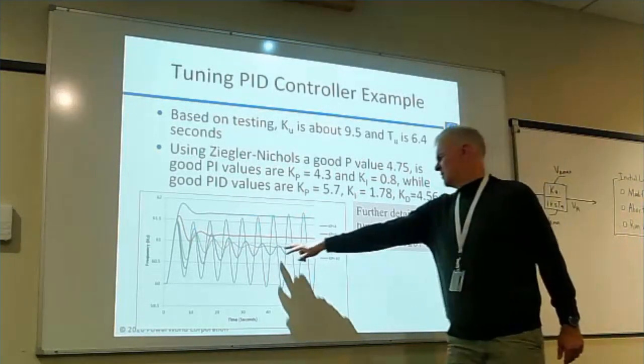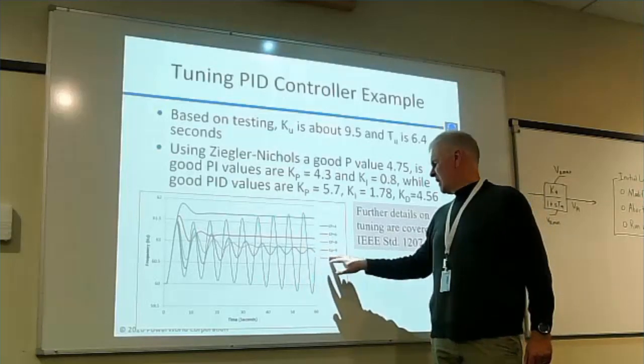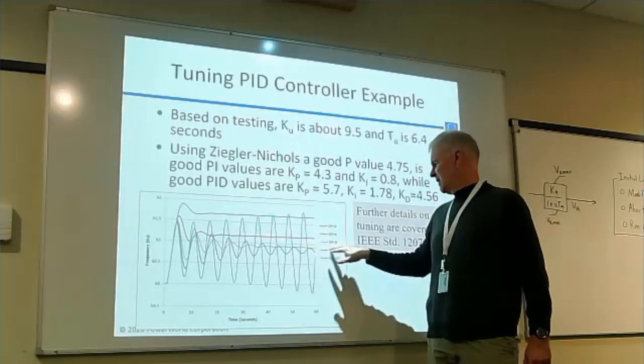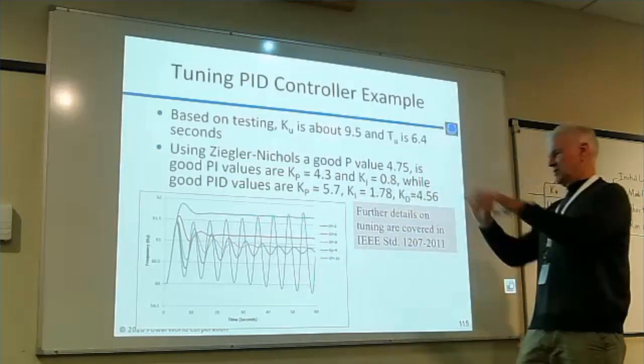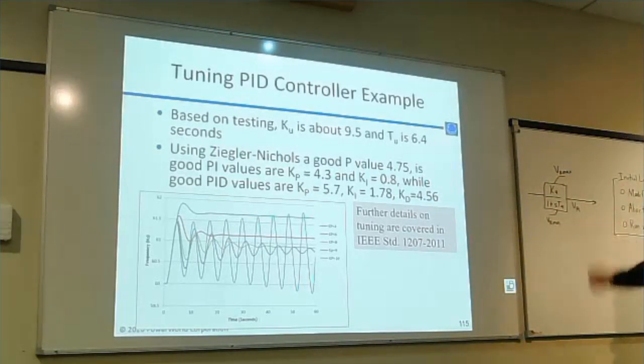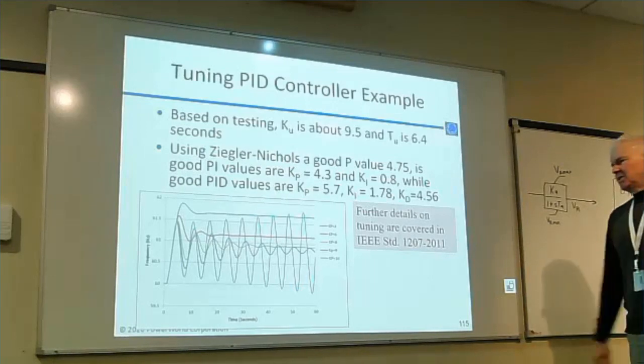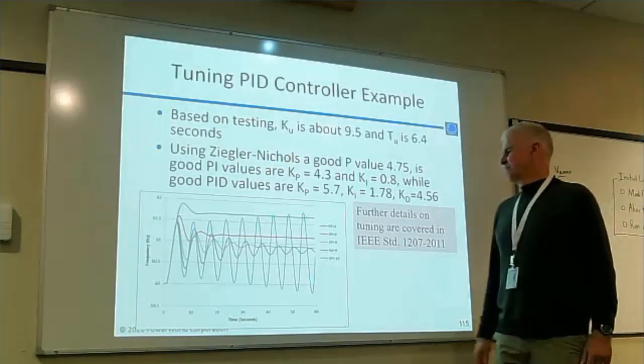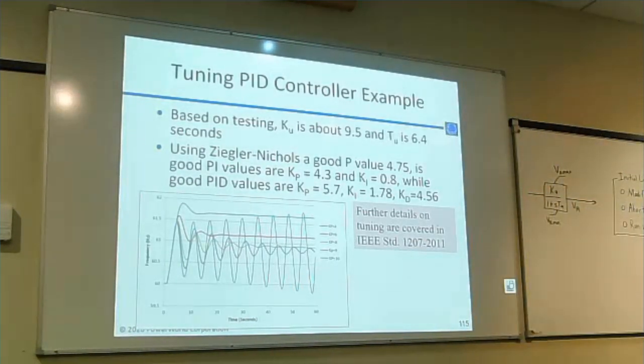So you can see when I had Kp 10, it was oscillating. At Kp 9, it was almost undamped oscillation. So that's where I got that Kp, 9.8 or something. Okay, so are there any questions on this? Somebody is tuning these things. And you can get a feel for how they should be tuned by doing this sort of testing.